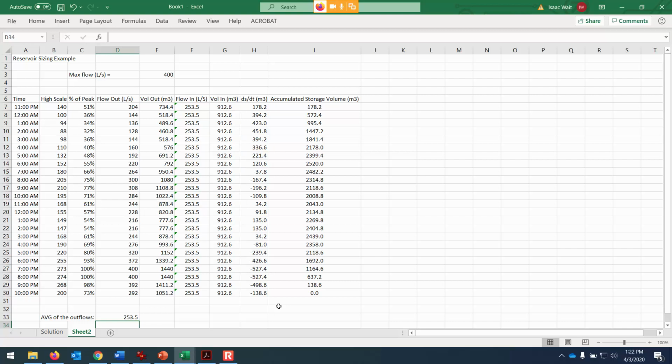And the constant rate that we assume for your project that it's generating water at is equal to the average demand on that peak day. So there's a steady flow into the reservoir, but a variable demand coming out of the reservoir. So the variable demand you get from the figure that you digitized. The steady flow into the reservoir is just the average of all of the demands.